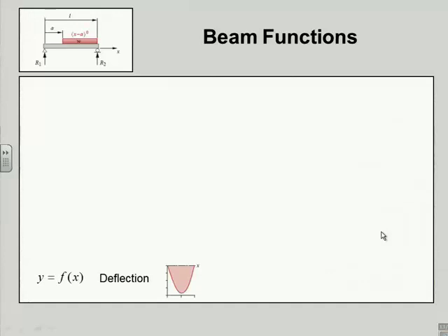So here we have a fairly simple beam in the upper left corner. It's simply supported, meaning there's just 2 supports. The little triangle gizmo symbolically means the beam is essentially on a knife edge there, and at the other end it's on a roller. If it gets a warm day and the beam warms up, it's free to stretch and not have any stresses generated in it by reason of the change in length between the supports. That's the purpose of that notation. Okay? So it says the only way I'm constrained is vertically.